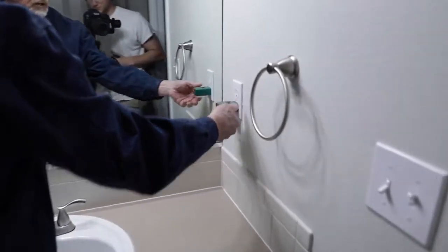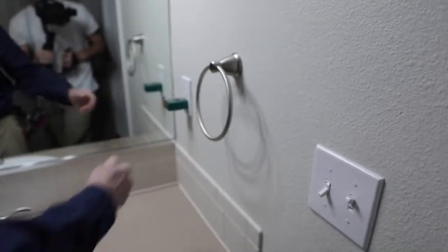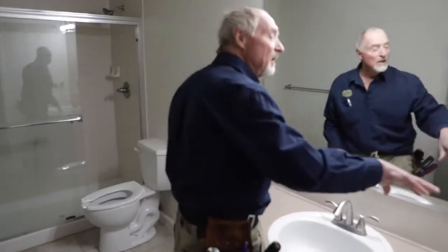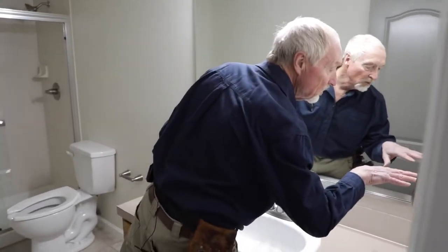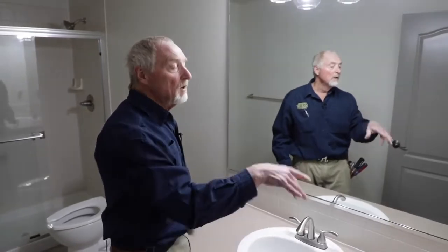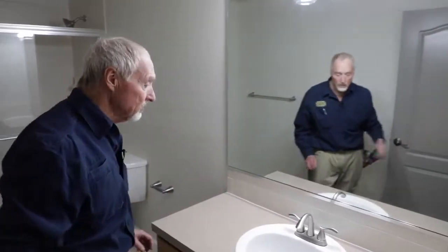And even though it's part of our electrical, we'll always check the outlet since I'm standing here and see if it's connected to a GFCI. And what do you know? We got the same problem we had up in the kitchen, some polarity issue with the disconnect, and it's showing a hot neutral reverse after I hit the test button. So this would be a defect that we would include in our report, even though that's technically the electrical section.